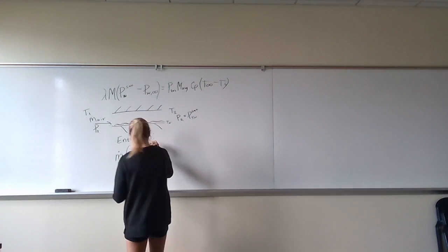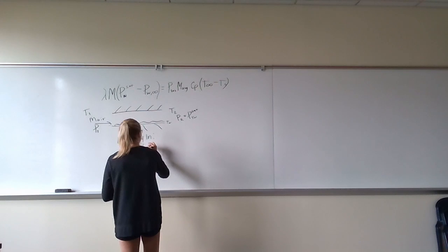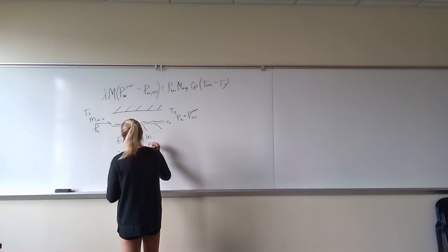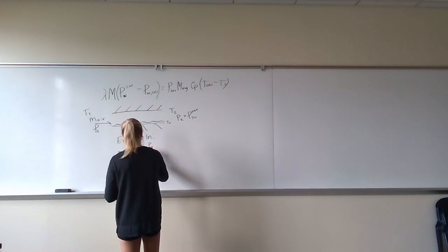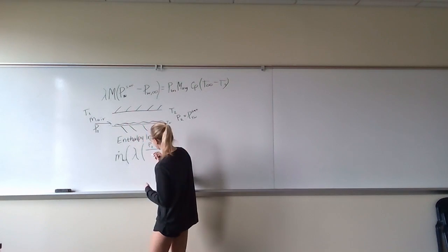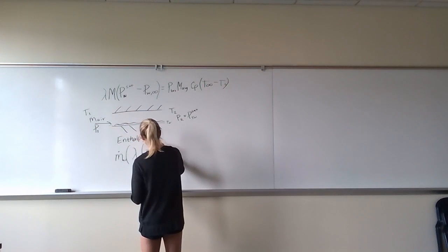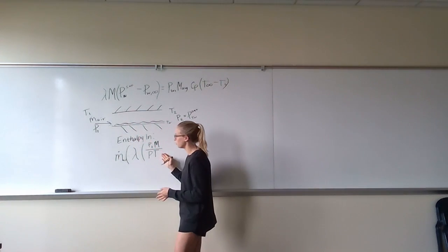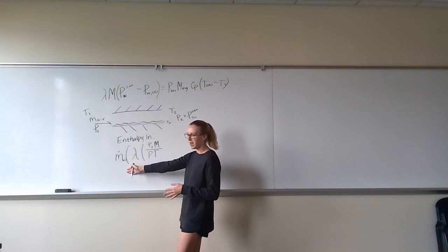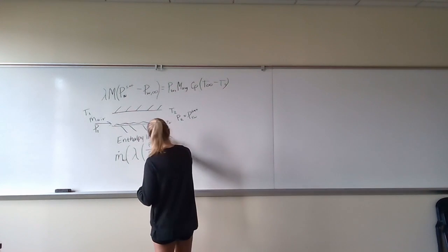So we can solve this by saying the partial pressure, or the pressure of the water vapor, P1, divided by the ideal gas constant times the temperature. And we want to multiply this by the molecular weight, since we have the mass flow rate, not the molar flow rate.